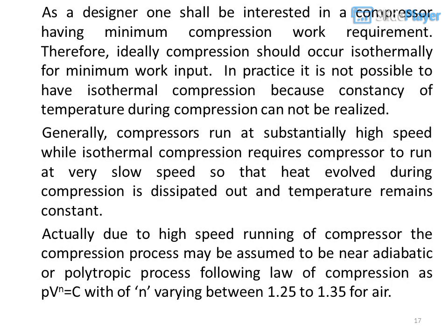As a designer, one shall be interested in a compressor having minimum compression work requirement. Therefore, ideally compression should occur isothermally for minimum work input. In practice it is not possible to have isothermal compression because constancy of temperature during compression cannot be realized.